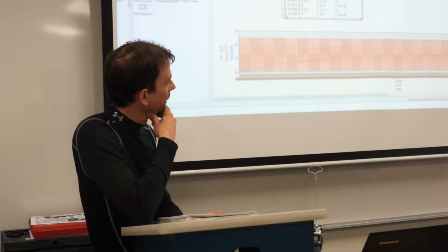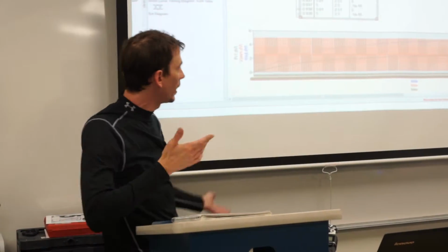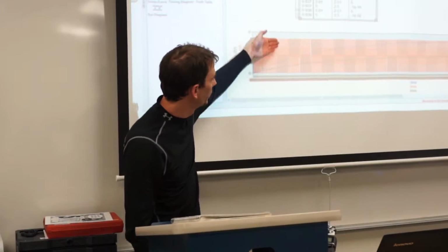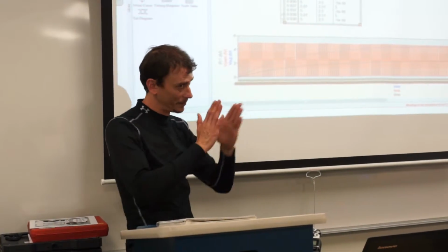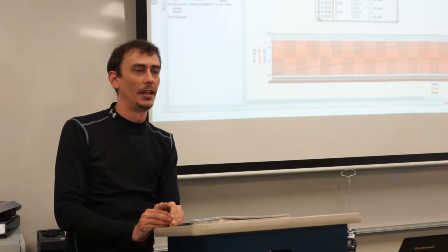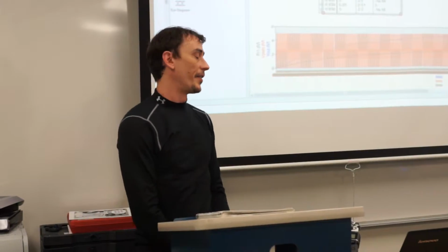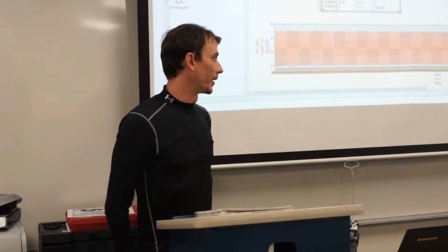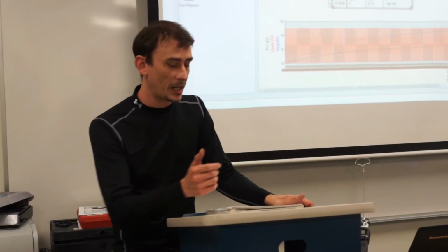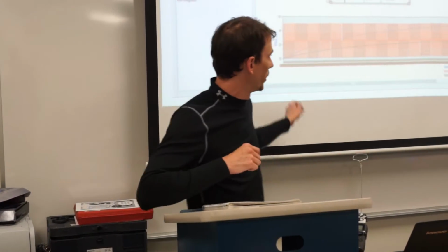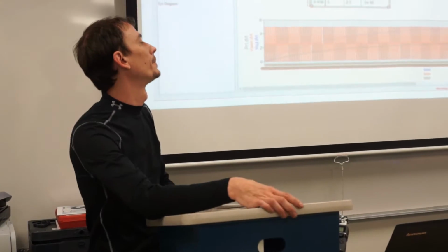Because as it turns out, it also has the effect of reducing noise, because when you double the clock speed, or you increase the clock speed, obviously your pulses get much closer together. There's much less time in between the pulses, so that noise has much less time to rise or fall. And that was very crucial. And if there's no limitations on the clock speed, we could get that noise to a very low level. We can have a very clean DC output as long as there isn't an upper limit on clock speed.